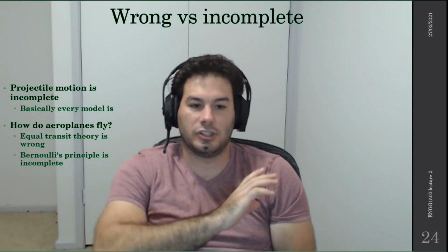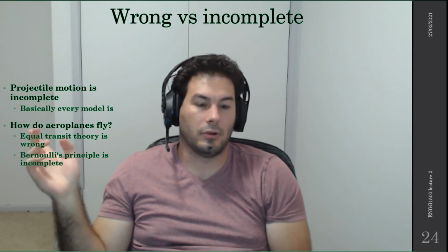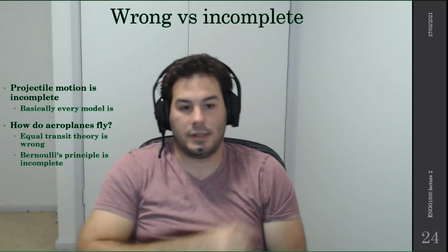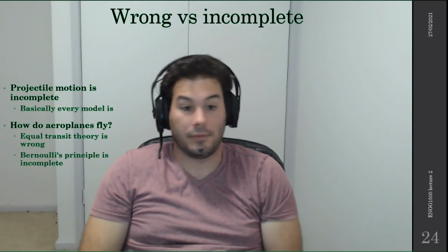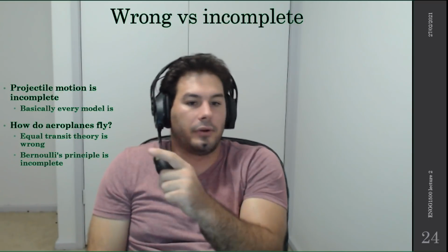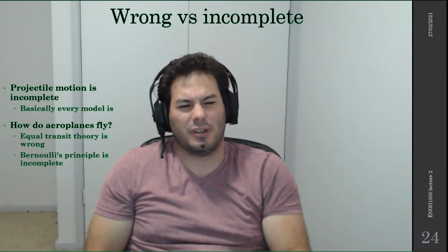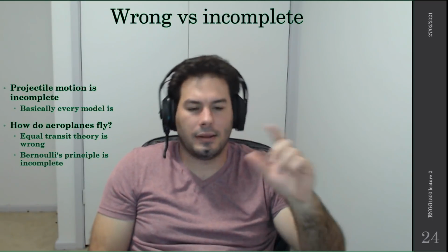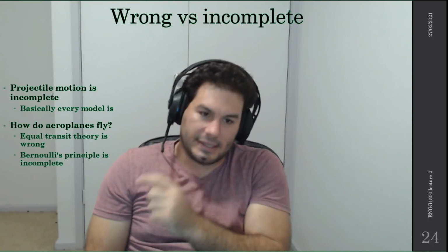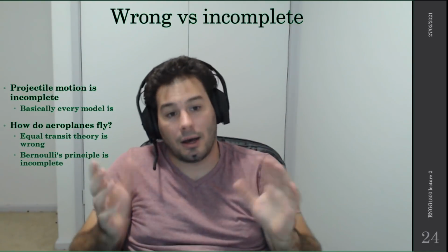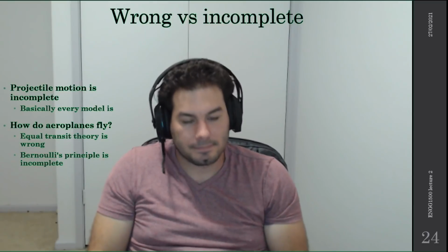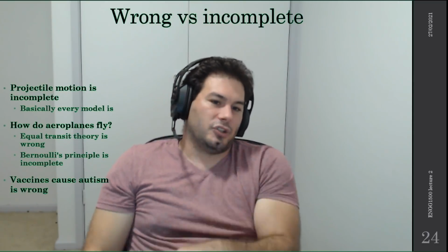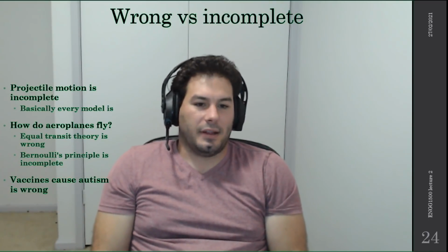And there's a whole bunch of stuff that can prove it, and if you're in mechanical or aero, we will show you the videos that fundamentally prove equal transit theory is wrong. It's in syllabuses and stuff. It's wrong. There's another explanation that says Bernoulli's principle and stream tube pinching. And it's not wrong, it's incomplete. Okay, so there are some subtle differences. So, using wrong as a catch-all, we should probably have a little bit more fidelity, and now we do.